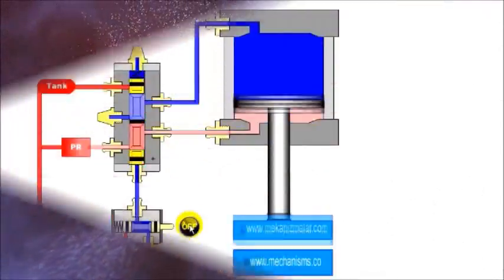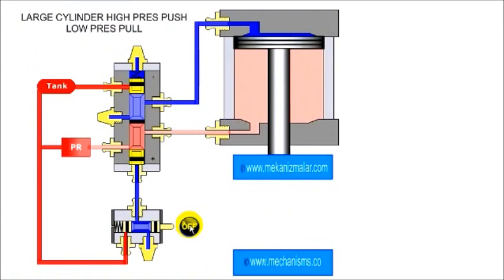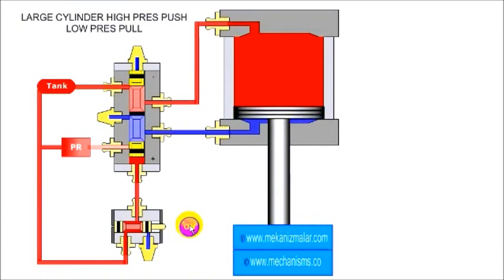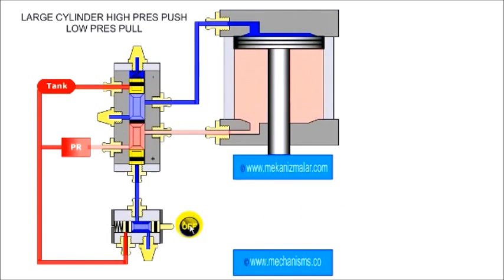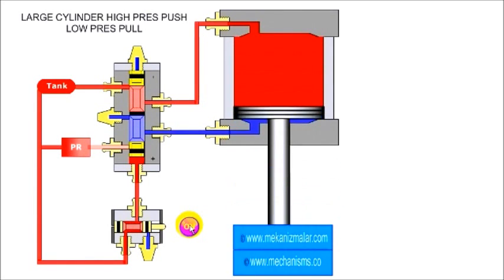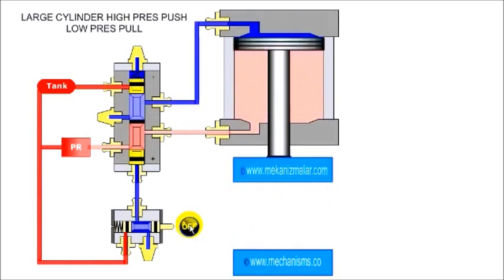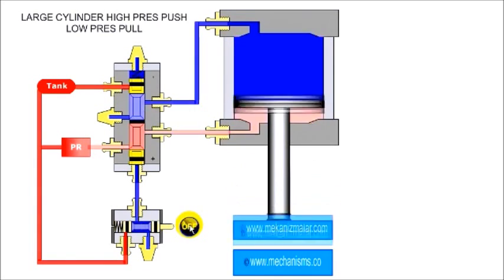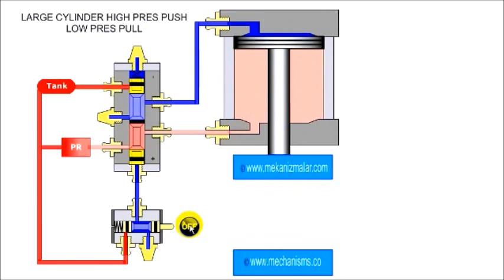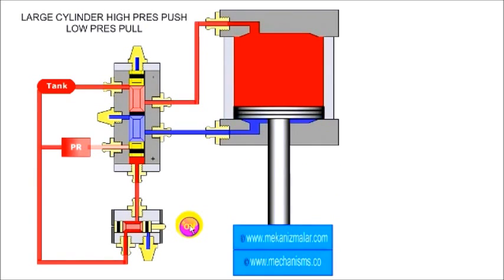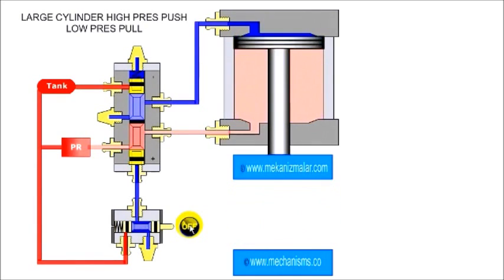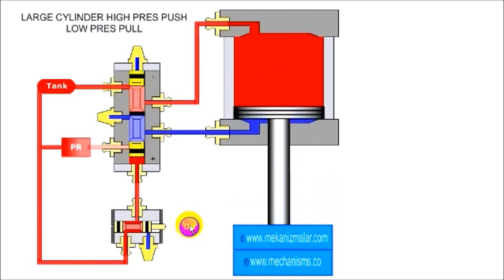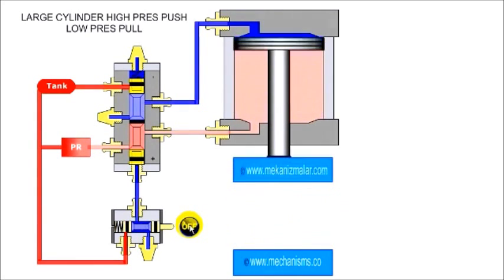The controller has the task of holding the controlled variable as near as possible to the reference variable. The controller constantly compares the value of the controlled variable with the value of the reference variable. From this comparison and the control response, the controller determines and changes the value of the manipulating variable.